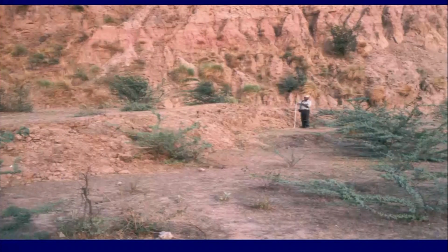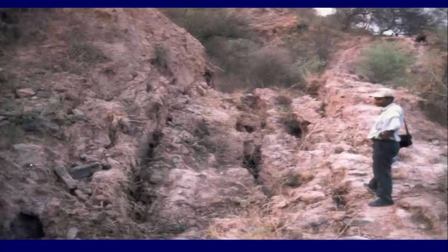We tried to gather and identify and understand what exactly happened here, and this is a very typical example of a rotational landslide. As we said, the rotational landslide at the toe portion will have deformation, but if you go towards the crown or the top part of the slope, then you will have an extension. So we looked for that, and this is what we found. There were extensional cracks, we were having scars. These are the scars here, there is another scar here, and then we have extensional cracks over here. So these are all extensional cracks.